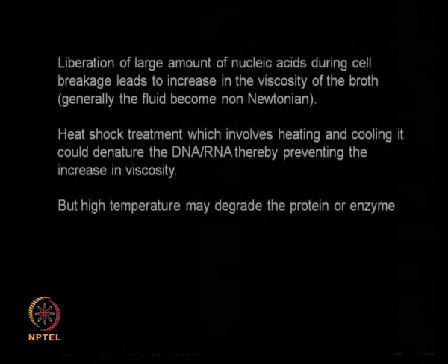So when you are breaking the cells, you are liberating a lot of nucleic acid during the cell breakage, so obviously they increase the viscosity. So when the viscosity is increased, it is not a Newtonian type of behavior, it becomes non-Newtonian, and handling non-Newtonian fluid in mechanical agitators, pumping non-Newtonian fluid is always a big challenge.